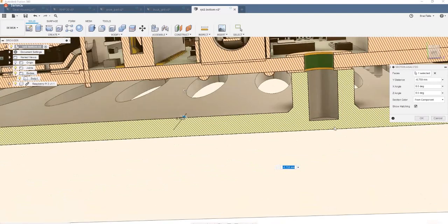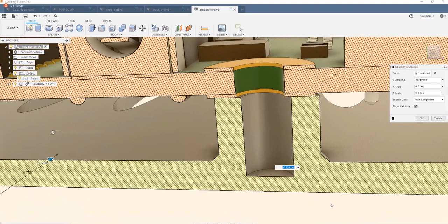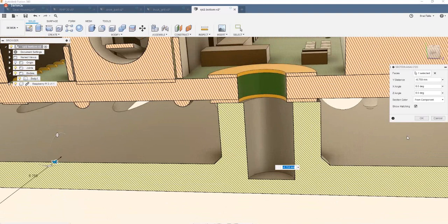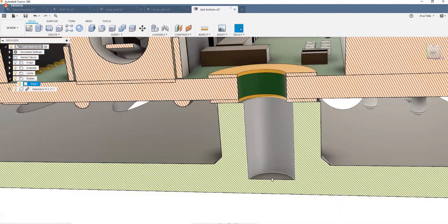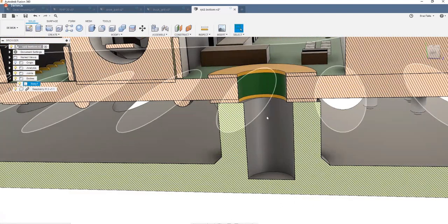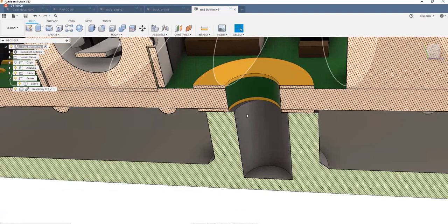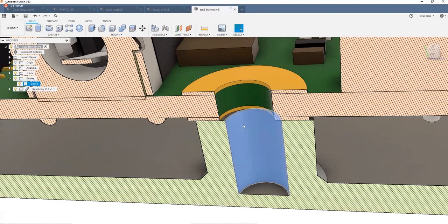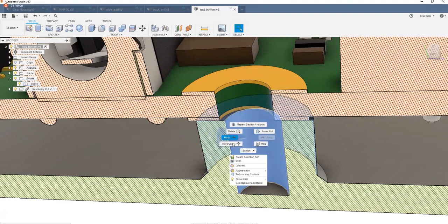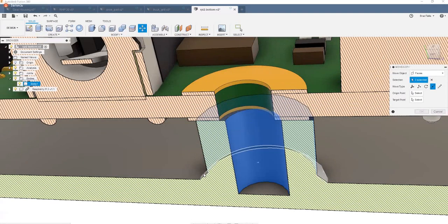But as I'm looking over here, that one looks like it's off by a little bit. So that might work. I could probably force a screw into there, but it'd be better to fix this. So I'm going to use direct modeling techniques in basically 2.5D. I'm going to select this face and that face at the same time. I'll say move. Notice I didn't select the chamfer. I don't think I have to.